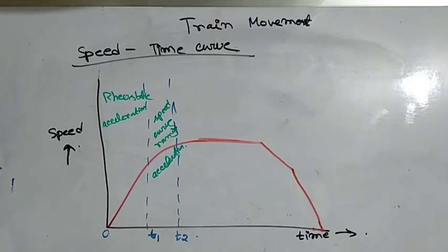And third cause is, as the speed increases, coefficient of adhesion decreases, and therefore the portion of the torque exerted by the motor which is usefully converted to tractive effort is reduced. Now the speed of the train will continue to increase to a speed at which tractive effort is equal to the train resistance, and train then will continue to run at maximum speed.